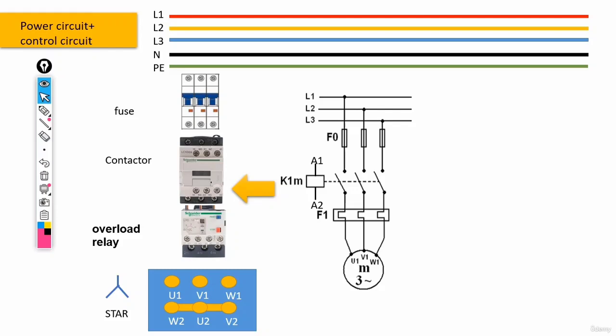All right, we said that usually we have a system like a three-phase system with three phase lines. Then we said that we can connect the phase lines to the fuse and then connect the fuse to the contactor, the contactor to the bimetal, and the bimetal to the motor at the end. So what we can understand from all of this is the fact that we actually need to start up the contactor. The contactor should be working. To do so, we need to connect a specific voltage to the bobbin of the contactor.